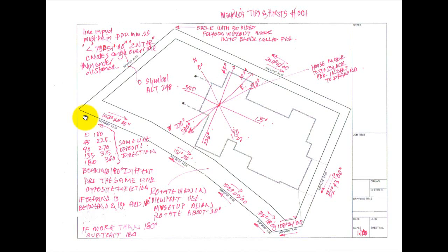Probably want to set the line width of your little circle and your polygon to 0, so that you just get nice crisp clear circles. So once I've created one of those, I just do a copy, type in CP, copy, center, and then I just copy it to all the other corners and put it over it.